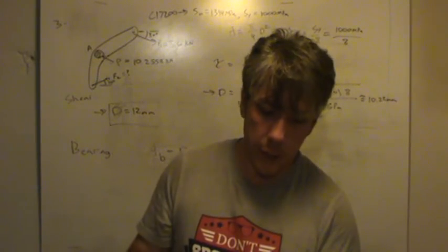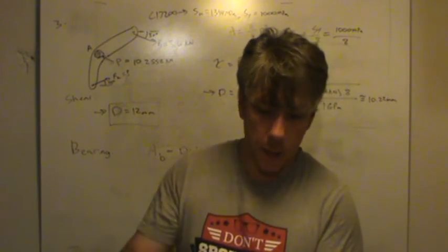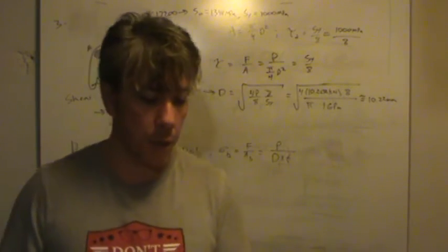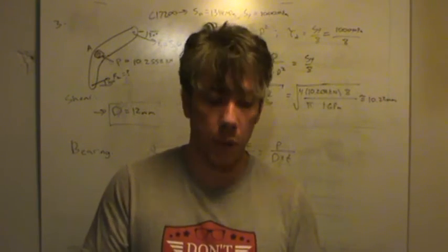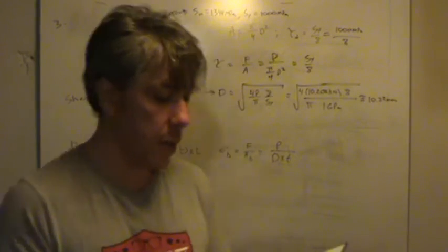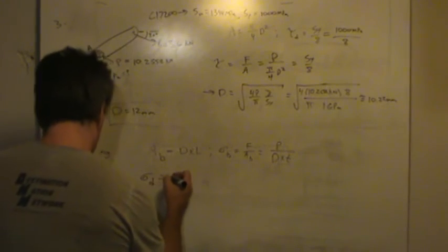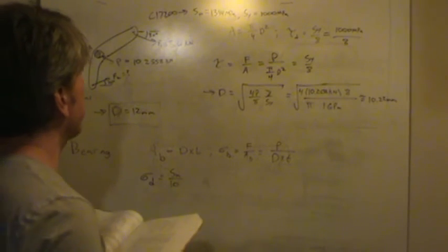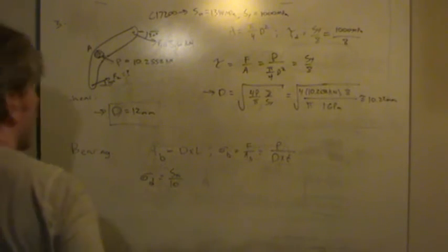in your book, early on in chapter 3, your author gave a table where he suggested design factors. Here we are, page 119, table 3-2. Now this is a repeated load, recall. And he has 2 columns here, one for ductile, one for brittle. Well, now we can just use the brittle material, which is on the right-hand side. Under repeated load, you'll notice that the design normal stress, sigma sub d, is equal to the ultimate strength of the material divided by 10. So that's the recommendation. So now we finally get to use this ultimate strength of that material.